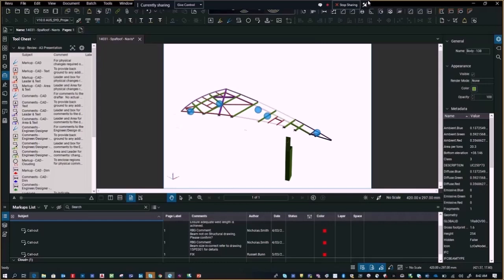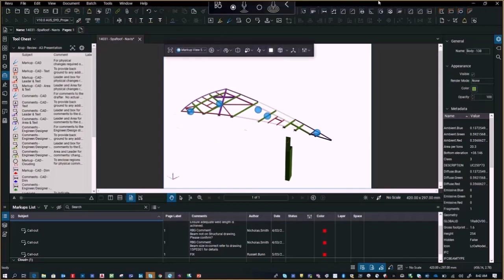In Navisworks, if you create a section box, it doesn't do that. You have to actually select the elements you want to export. So usually I create the section box in Navisworks, then use the rectangle tool, select them all and export those.